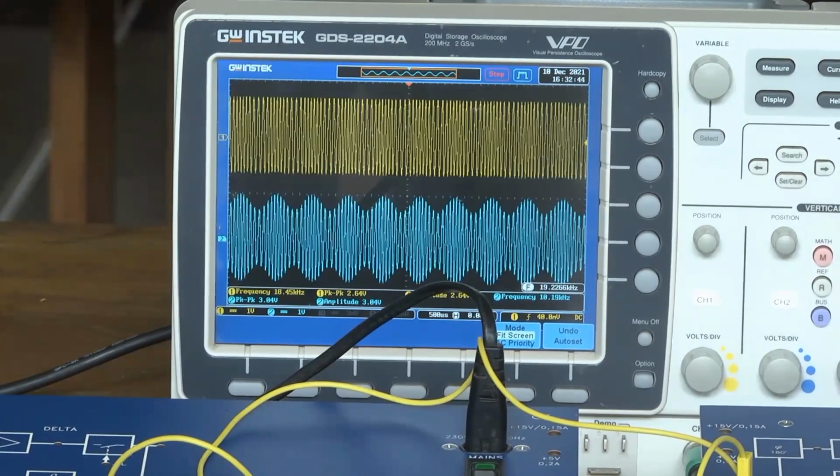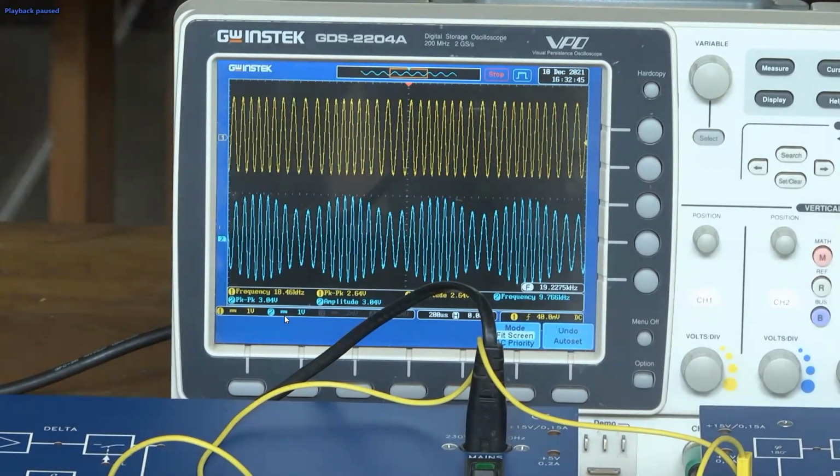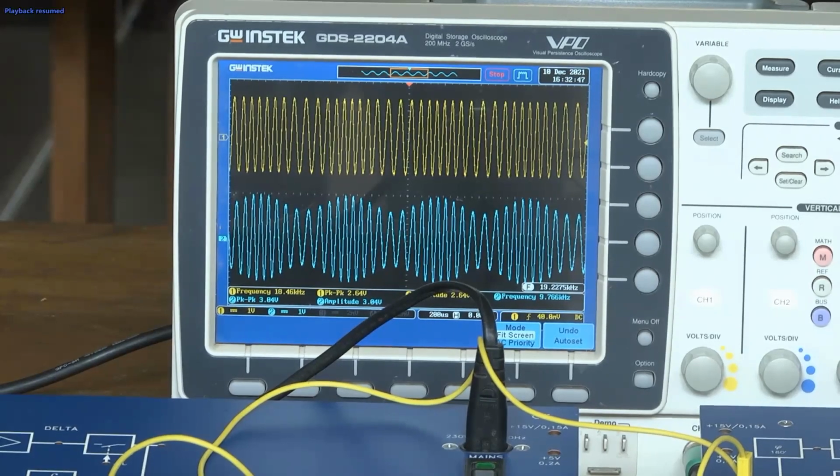Here you can see this is the modulated signal. You can see the frequency is higher here, and lower here. This is the modulated signal, and this is the output we got from the discriminator. So it acts as the slope detector. When the frequency is low here, the output becomes low. When the frequency is high, it becomes higher. It's like an amplitude modulated waveform. We can take this output from the discriminator circuit.